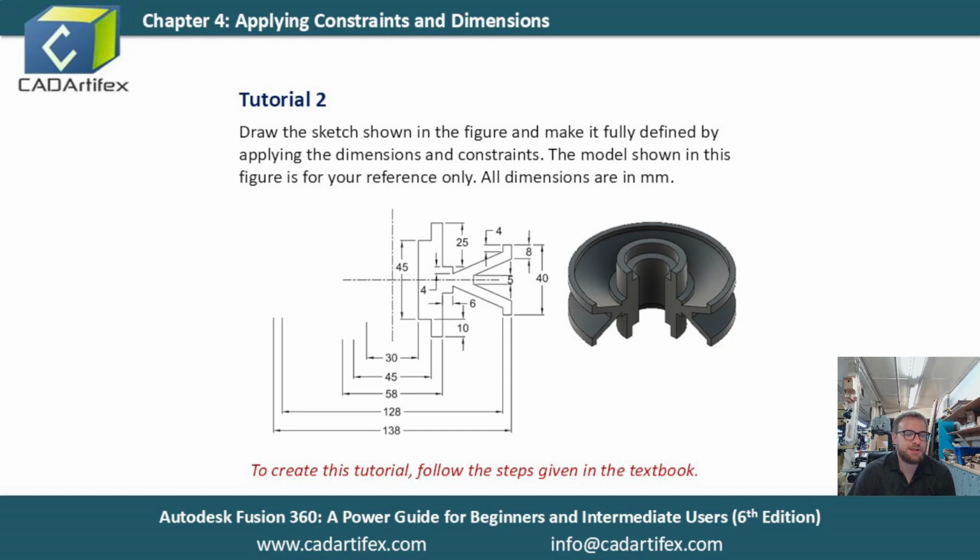So we have this shape that has two types of symmetry. One, we have a vertical symmetry where we can define half the shape and then reflect it down below, or down below and then above. And then another is that later, the cross section that we make would be revolved around the central axis. So to do that, we'll go ahead and draw in the axis, although we won't do the revolving. That's saved for a future chapter.